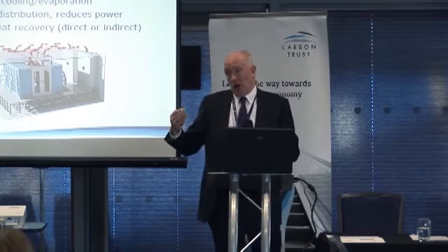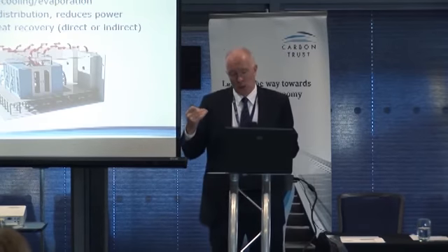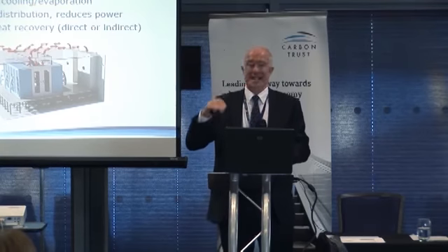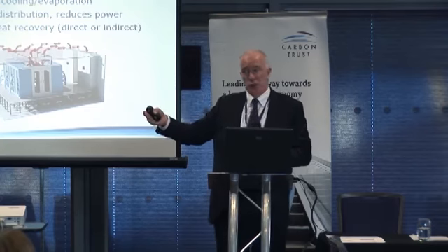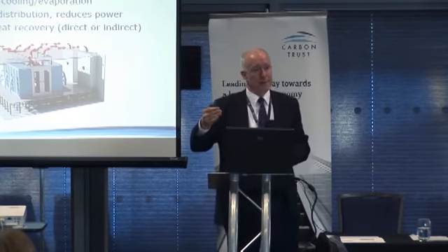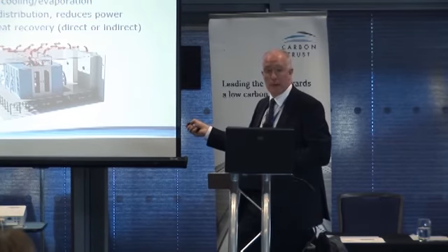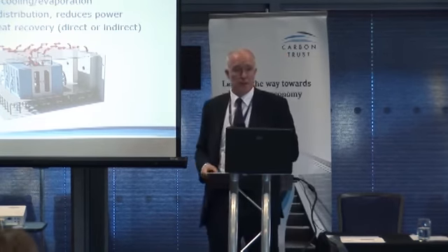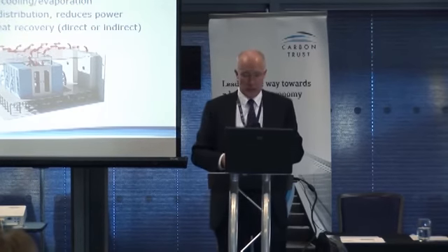The hot air will be a larger volume, so you generally do not contain the hot air, you contain the cold air. But the advantage of containing the hot air is that if you did want to do anything with regard to heat recovery, hot air coming off at 30 degrees centigrade is a very useful temperature for space heating. So if you did want to do anything with heat recovery, you can heat recover from here. And if you were using fresh air input and output to do your natural ventilation chilling, you could direct this to the building if you could use it usefully for space heating. So containing the hot air has a value there as well.